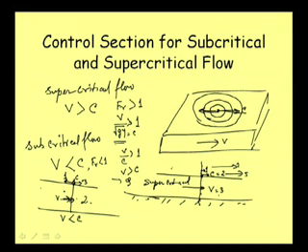This is moving with a velocity V, and C is faster than this, so the wave is moving far ahead of the velocity. So this is not getting affected in the upstream part, downstream part. At downstream this will not be affected as such, and at the control section there will be influence, but so far as the control is concerned, in case of subcritical flow we get it on the downstream side, and then at upstream this will influence the upstream flow.